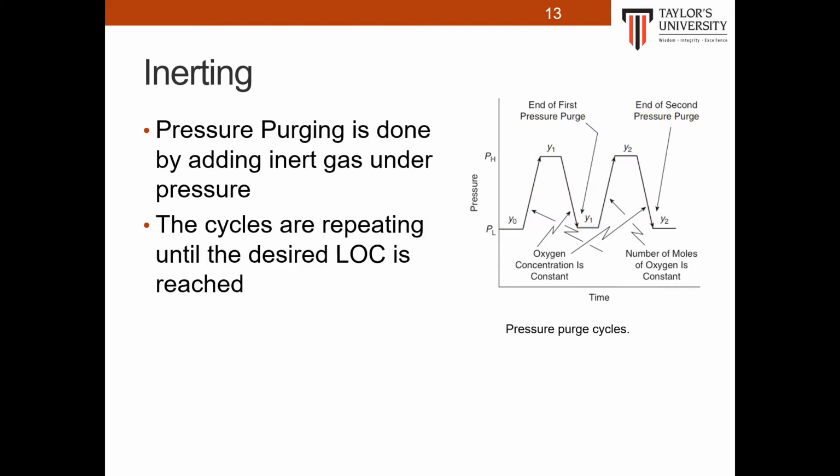One of the practical advantages of pressure purging versus vacuum purging is the potential for cycle time reductions. The pressurization process is much more rapid for pressure purging compared to the relatively slow process of developing a vacuum. Also, the capacity of a vacuum system decreases significantly as the absolute vacuum is decreased. Pressure purging, however, uses more inert gas. Therefore, the best purging process is selected based on cost and performance.